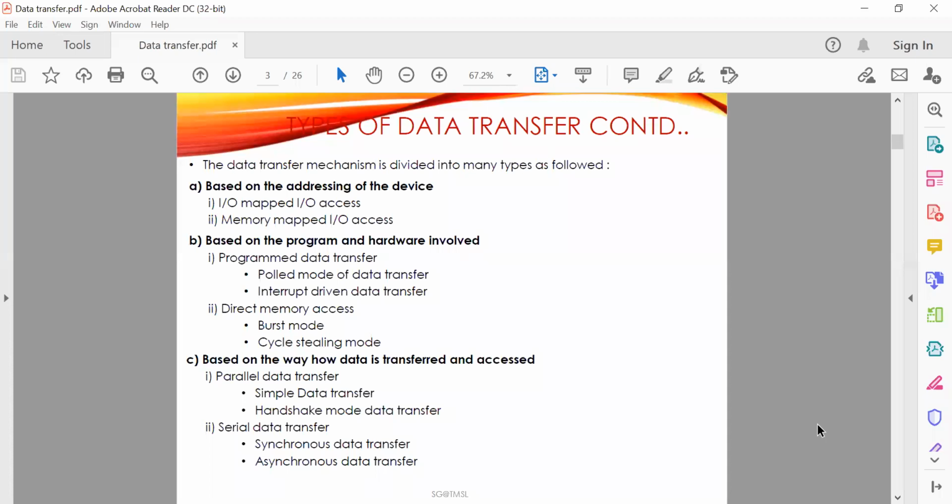That is the controller device which is most commonly used with the 8085 or any processor. It is a four channel device, with each channel capable of addressing 64 kilobytes of memory, and each channel being dedicated to a particular peripheral device.